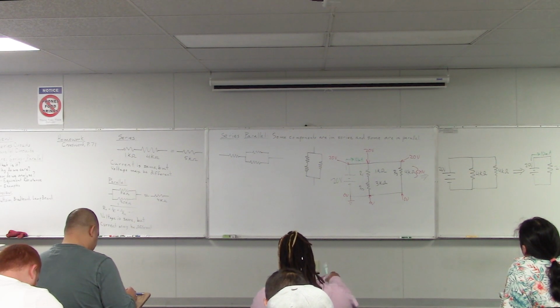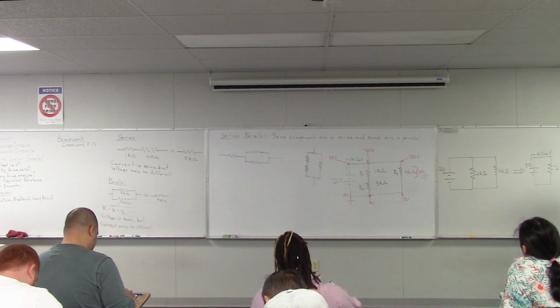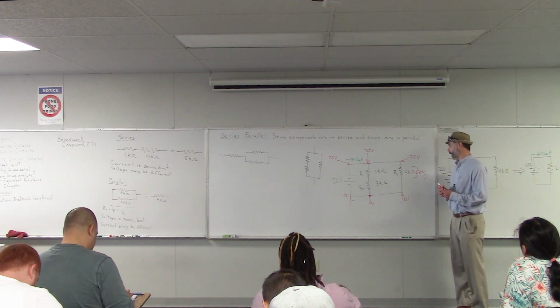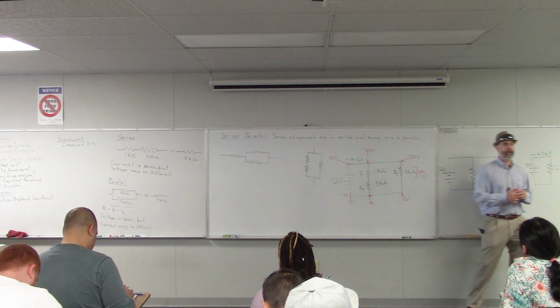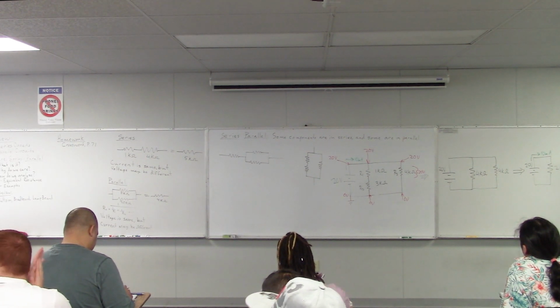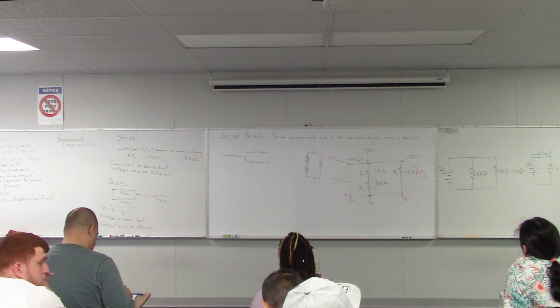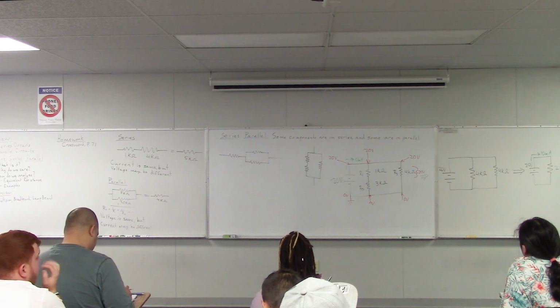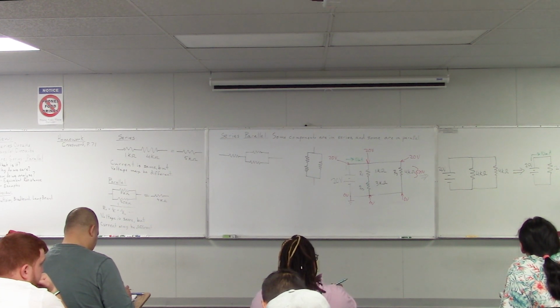So we can use that and write down the voltage for R3. That's 20 volts. And now we know the voltage and the resistance there. So can we figure out the current? Yeah. And what law do we use for that? Ohm's law, exactly. So we want to figure out the current here again. We use this formula, V over R. The voltage here is 20 volts, and then the resistance is 4 kilo ohms.